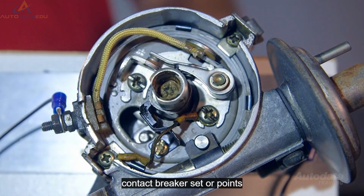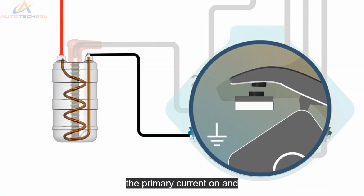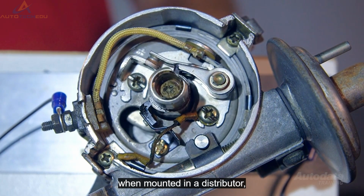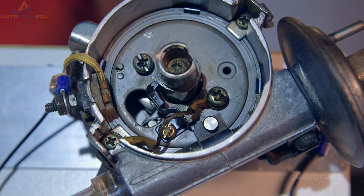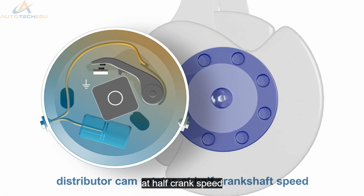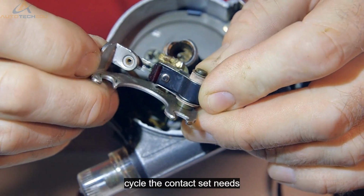The contact breaker set, or points, is in reality just a mechanical switch. They are only there to turn the primary current on and off. The contact set is designed to be opened by a cam lobe when mounted in a distributor. A 4-cylinder engine would have 4 distributor cam lobes, one for each cylinder. The distributor is connected to the engine crankshaft or camshaft and is geared to turn at half crank speed. This distributor cam lobe opens the points via a follower block 4 times per engine cycle.